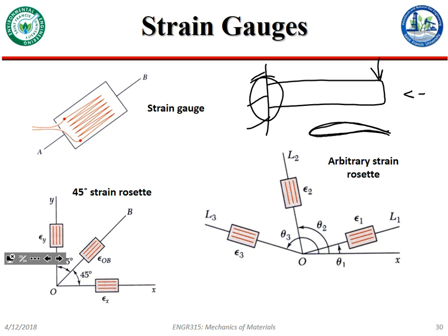Because of how this force is being applied, and how loads are being transmitted in a somewhat strange way, with a really curved surface and a whole ton of rivets along this thing, there's not really an intuitive way to figure out what the actual stress distributions are. So the easiest way to figure out what's going on is actually not to compute stress, and we can't really measure stress in a way. The easiest way now is to compute strain, or measure strain, really.